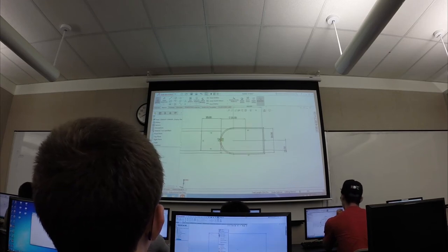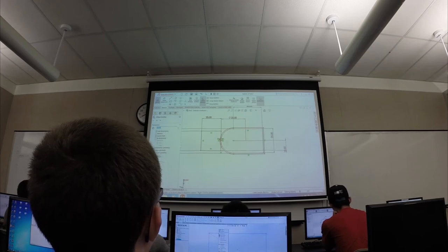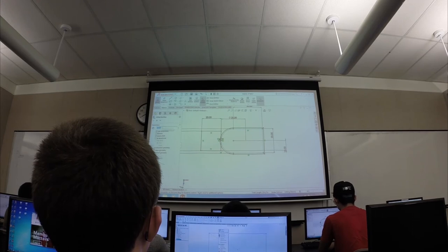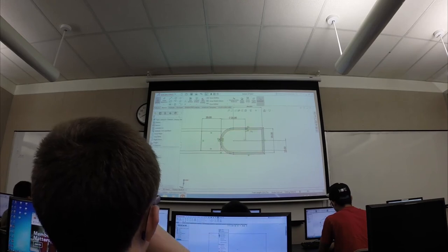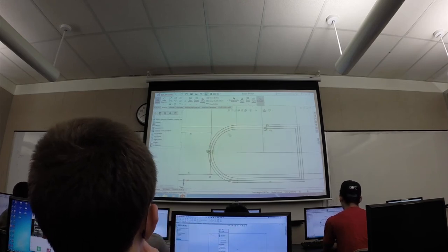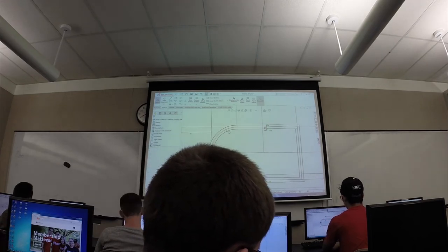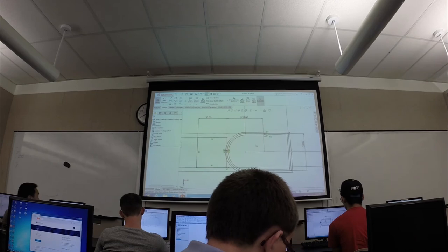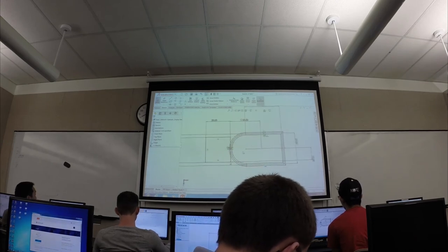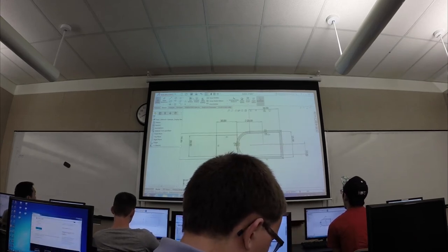So if I were to do offset again, instead of offsetting outwards, you could click this reverse box, and then it'll project the preview of the offset inside your original sketch. Click OK, and now you have 3 sketches that are offset from the center one right here. So this is just to play around with it. It serves no real purpose at the moment.